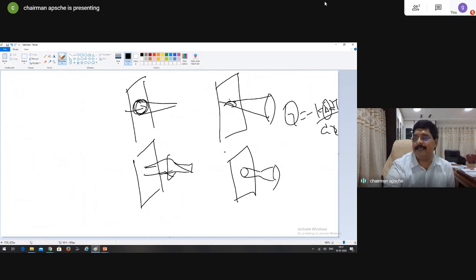Now, even in this case, the heat transfer after this will be effective only up to the center, and at the center the area is reduced, and therefore heat leaving the center will be minimum. Even that is not preferred. And there's no point in adding higher cross-sectional area because when lateral area is high, cross-sectional area is also high.